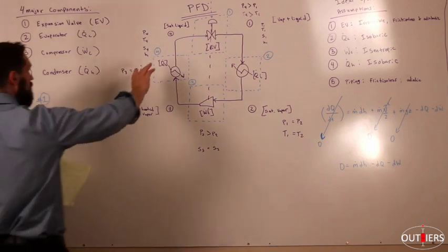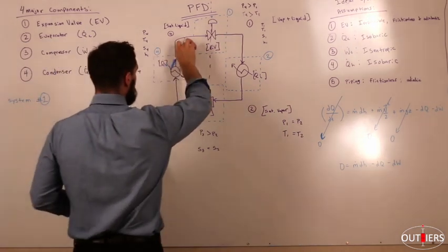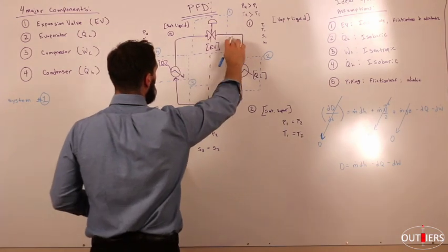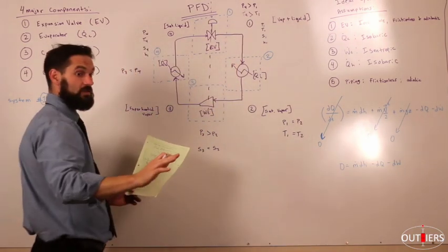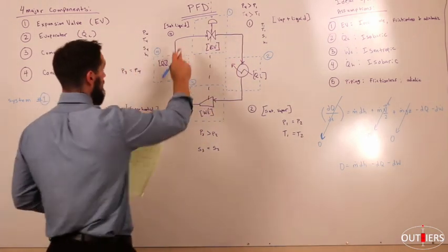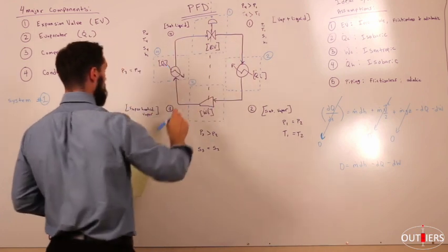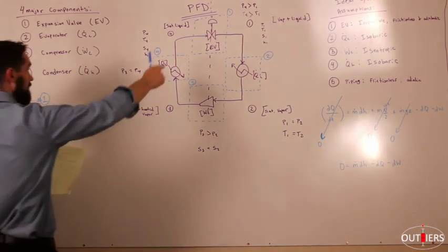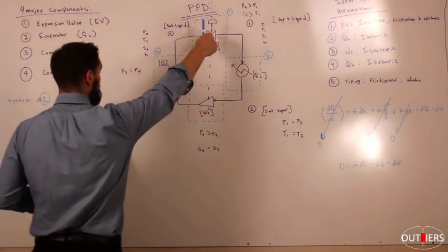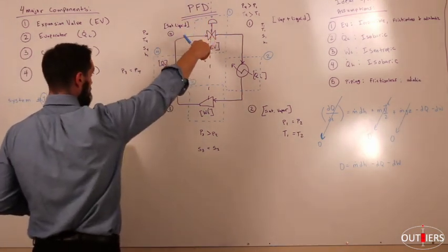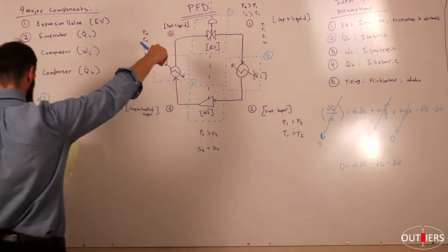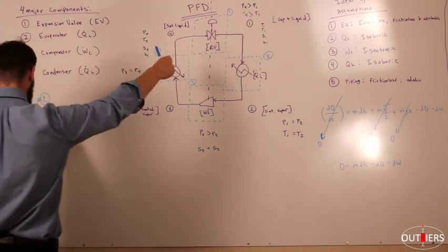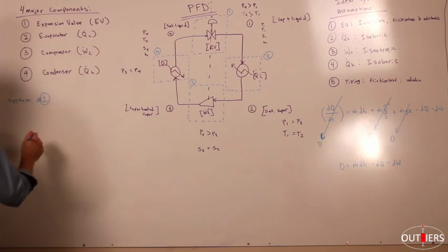And what's happening? We have fluid coming in here, fluid coming out here. No mass is lost, right? The mass coming in is the same as the mass coming out. There's no work being exchanged, so the valve isn't, there's no work happening because remember we assumed that it's frictionless, some of our ideal assumptions. And there's no heat exchange.